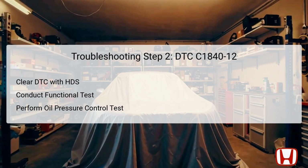Once cleared, the technician should proceed to select the functional test option in the real-time AWD section of the HDS. This functionality will help to conduct an oil pressure control test, which will reveal how effectively the system can regulate the pressure. Observe the results of this test closely.